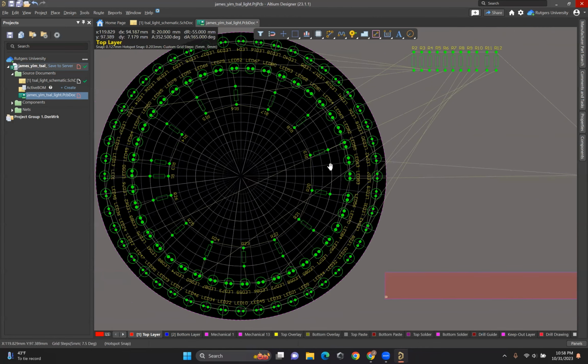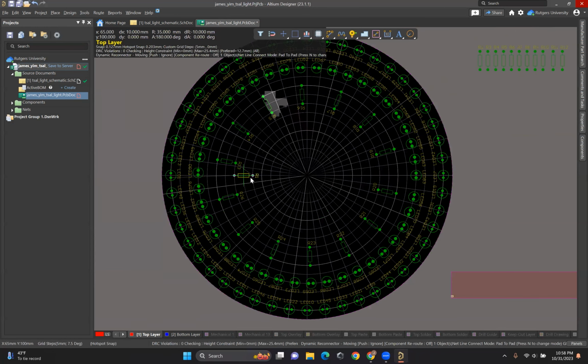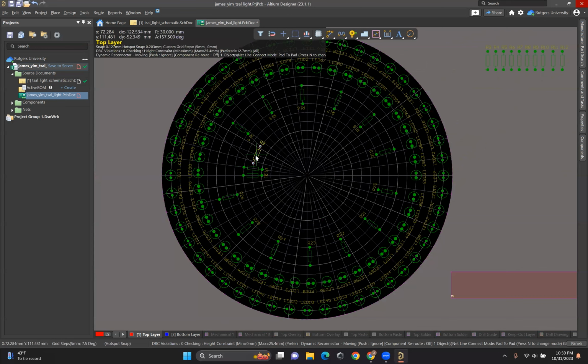All right, so now you can see I already put down one of these resistors, but I'm just trying to keep these close to the center, as compact as possible. I'm going to put them on this polar grid, just because it's a smaller angle. We're going to be able to space more in. But it's the same principle as the others. The spacing is really just looking at how the nets line up, like this line that's above this resistor, and you just try to get it as concise as possible.